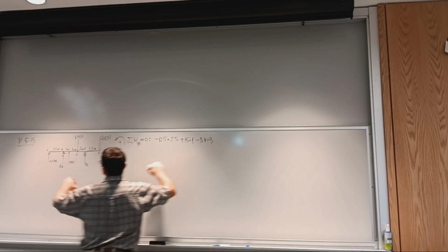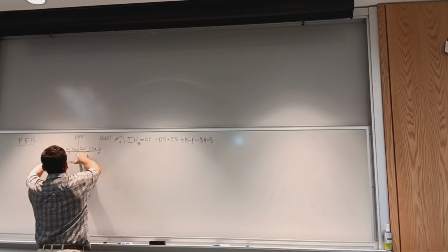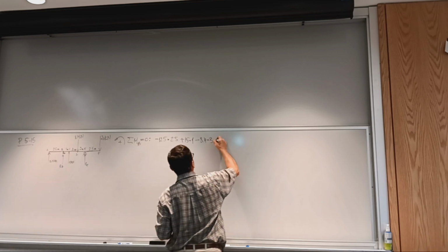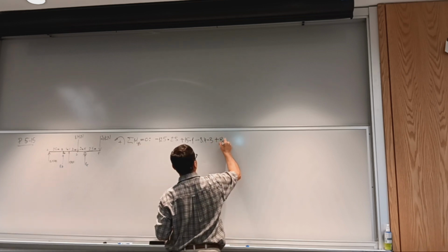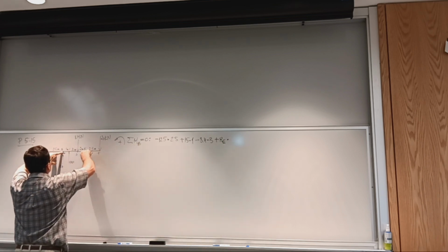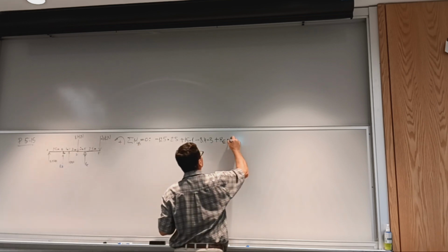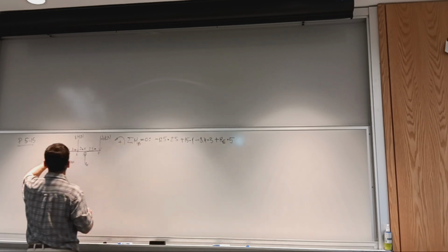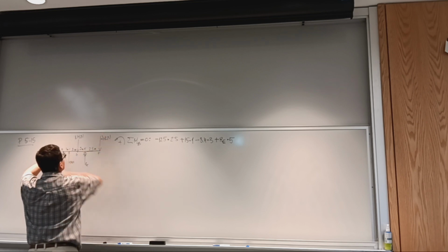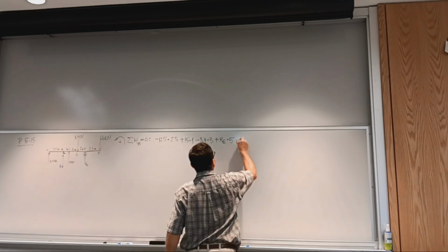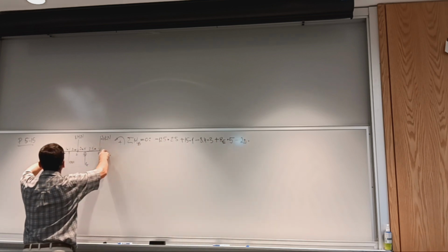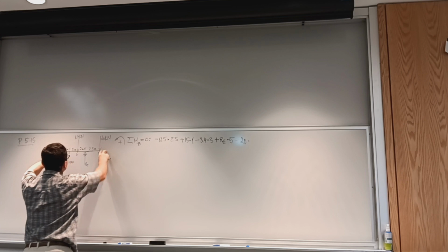Then I pass point D and I'm at point E where the reaction is, and the reaction generates a positive moment. So it'll be RE multiplied by the arm of the force, which is 2 plus 2 plus 1, that's 5. Okay, and the last force acting is the one at point F, the overhang, and it creates a negative moment. So I have negative 20 multiplied by this whole distance. It will be 1 plus 2 plus 2, that's 5, plus 2.5, that's 7.5.